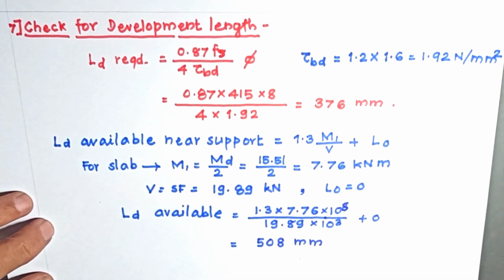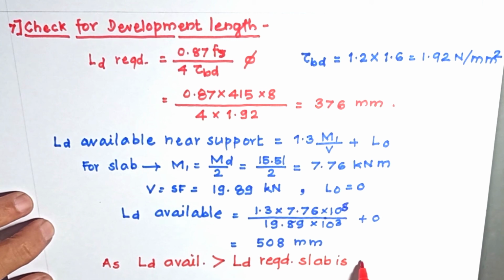As now you can very easily say that as LD available is greater than LD required, slab is safe for bond, flexural bond.